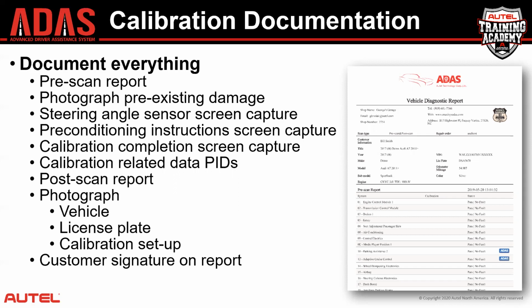Then when you're performing a calibration, at the very end, you'll get a screen on your scan tool that says calibration completed successfully. You want to do a screen capture of that and add that screen capture to your post-scan report. Sometimes you may forget to do that screen capture. That's okay. You could go back into the module that you calibrated and look at live data PIDs and find the PID for calibration status. And if it says calibration completed or calibration success, you could do a screen capture of that and add it to your post-scan report.